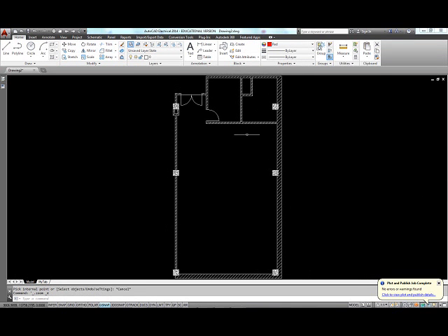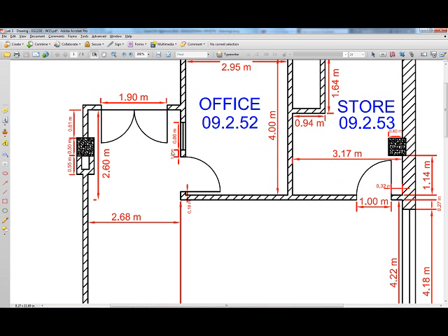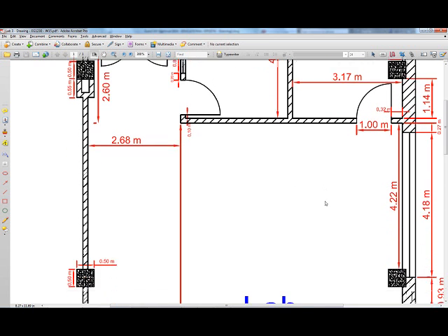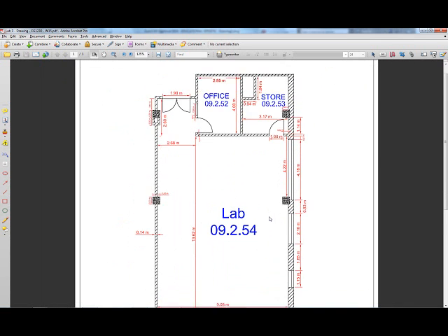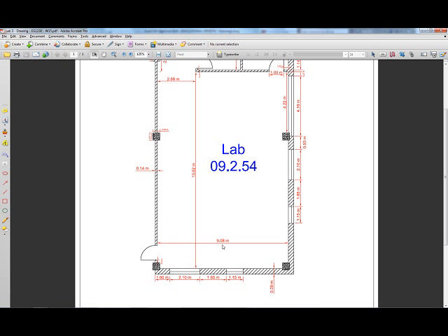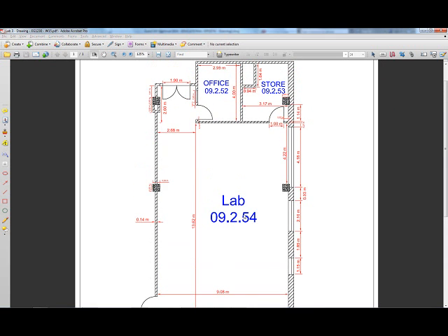And the other doors are pretty much the same as this door. The windows are simple; you have to use lines as well as the trim command to clear these areas. Remember, you have 1, 2, 3, 4, 5 windows to complete. So good luck and exercise well. See you in the next clip.